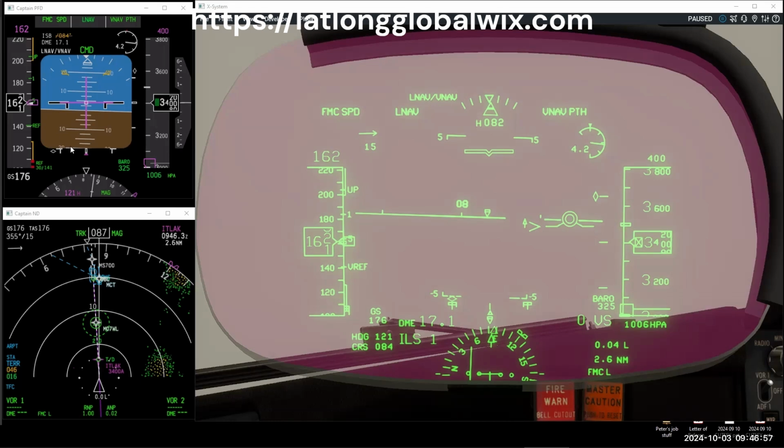Let's go over to the indications that we have for the nav for this RNP AMP. If you look at the bottom of the nav display, the RNP is 1.0 and the actual nav performance is 0.02. And if you can remember from the PowerPoint, the RNP changes depending on whether you are overseas, en route, in the terminal area, or on approach. And the AMP is the actual performance. So we're well within the scope of actual performance.